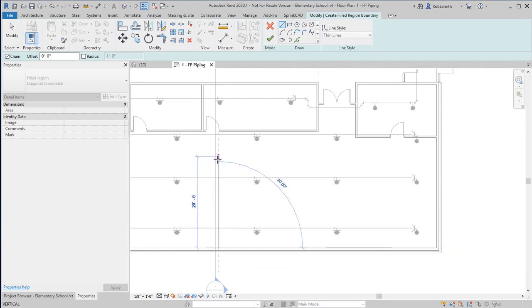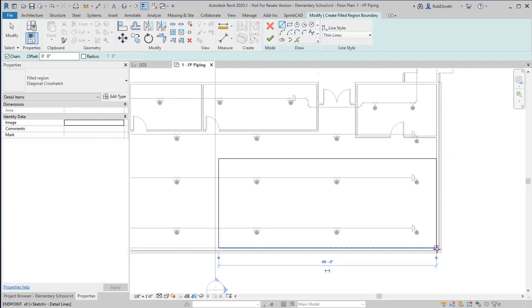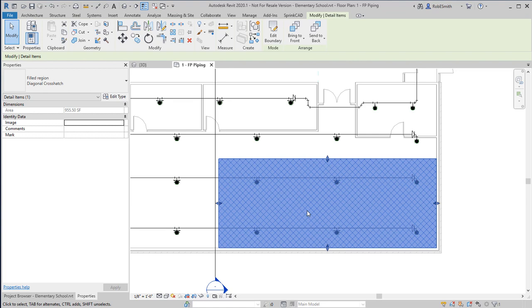I'm going to come across the room halfway between the second and the third branch line. Now, when I say branch line, I actually do mean the sprinkler heads. So I'm eyeballing this. If there are better ways to do it in Revit, I don't know them yet. I'm looking at 19'6", perhaps 20 feet. And if I do the math on that, I believe that just those 2 branch lines are going to satisfy the 900 square feet. We'll check it by finishing this space.